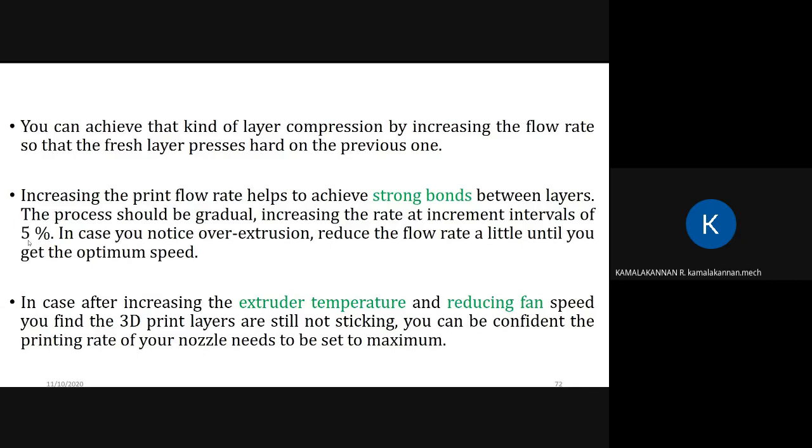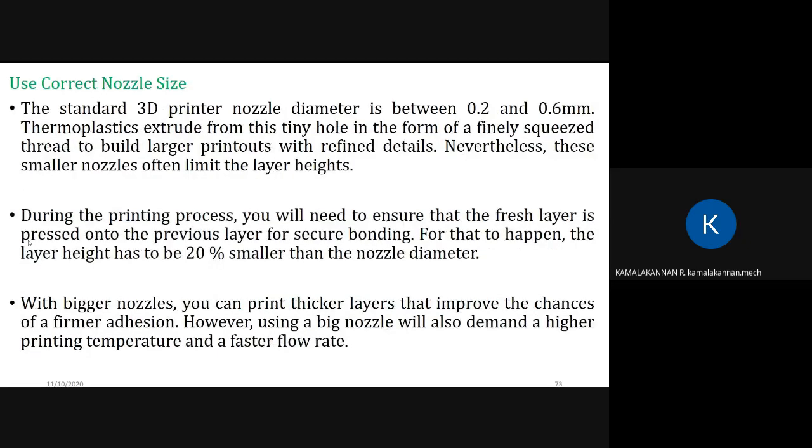Use the correct nozzle size. It depends upon the size of the product. Choose the correct nozzle so that you will have a proper output. If you have intricate shapes, complex shapes, or some thin areas, you have to go with thin nozzles. But if you have a general product, a common orientation product, you can go with a higher diameter nozzle. So it will be easy for you.